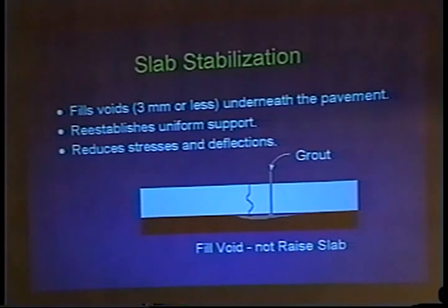It's real important. You want to fill the void, but you don't want to raise the slab. It's not slab jacking. With slab jacking, you would bring it up and it would give you non-uniform support, and then you'd have problems on top of that. So all you're doing is trying to just fill the voids with a method such as this.